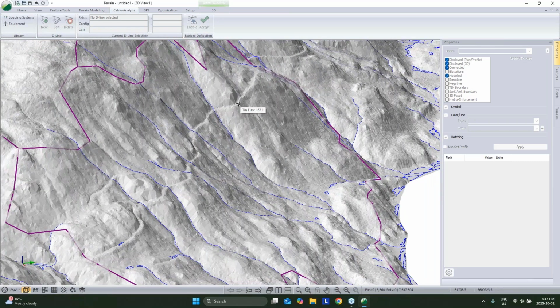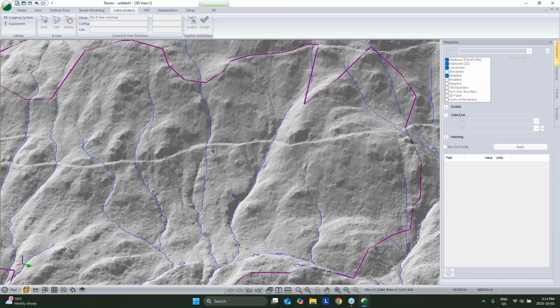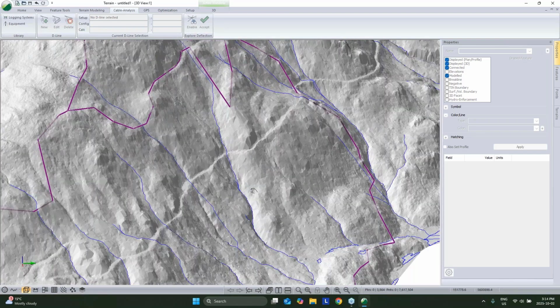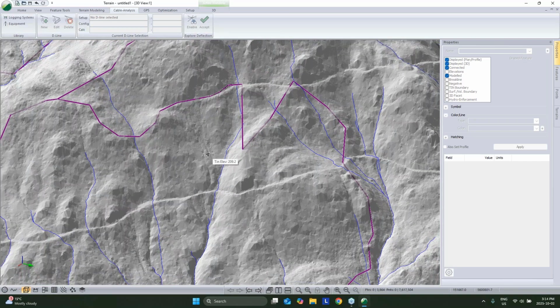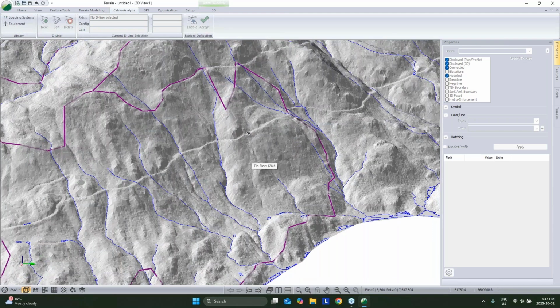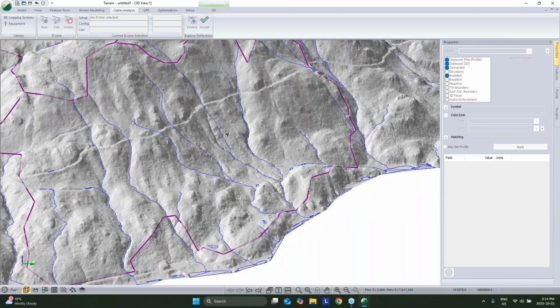So if we wanted to explore other options, we could use these tools to do that and maybe explore a location where it'll give us lots of room to deck wood and maybe even build out a nice big landing to make our lives easier. And then the other side of it, aside from just the decking challenges, it's really steep along here. We can see that the existing road has failed in some spots, and even upslope here, we've got this failure here. So aside from just advantages of having more room to deck wood, we might be able to avoid some really difficult terrain. That's risk.